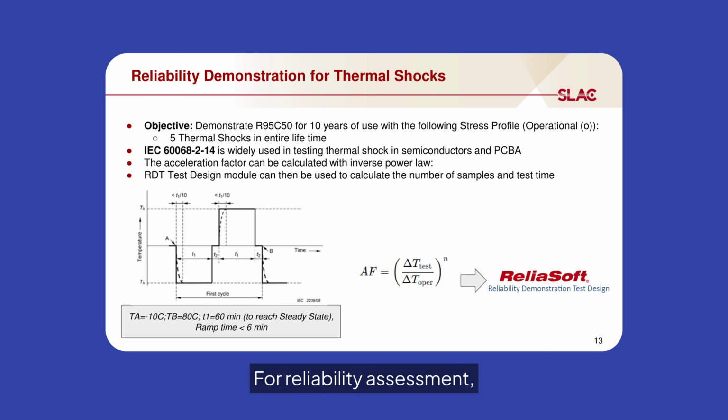For reliability assessment, the acceleration factor associated with thermal shock severity can be estimated using an inverse power law relationship, consistent with strength and fatigue-based failure models.